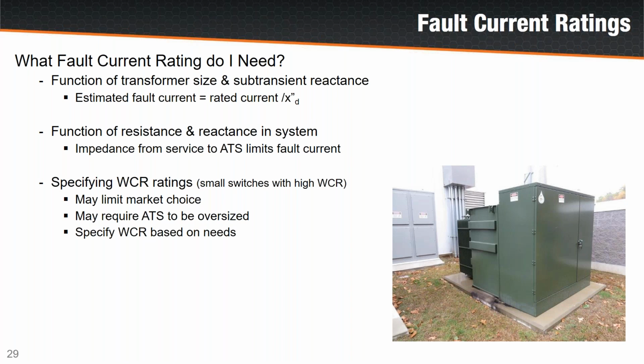The cabling from the transformer to the distribution panels, and then from the distribution breakers to the transfer switches is going to attenuate that. So when you plug the elements into your SKM software, you can actually calculate the available fault current at the transfer switch. So at that point, you need to make sure your transfer switch has enough fault current rating for what's available at that point in the system.